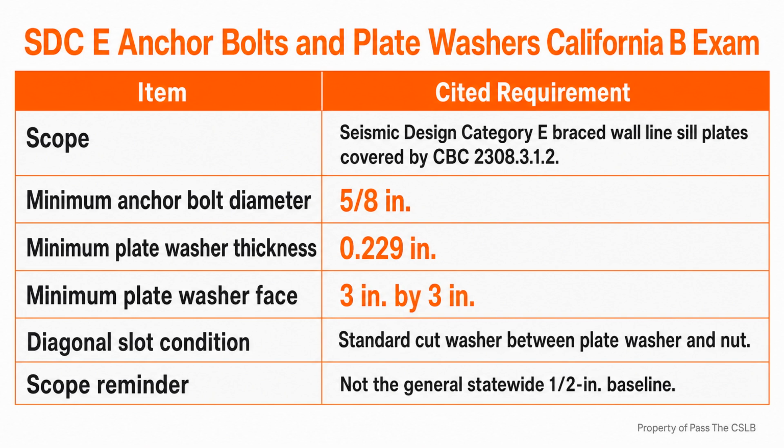The load path can still be broken above the foundation even when every anchor bolt is perfect. California Residential Code Section R502.2.1 requires a specific lateral force path between horizontal floor framing and vertical braced wall panels. The force gathered by the floor cannot simply arrive near the wall. A connection has to transfer it into the wall.